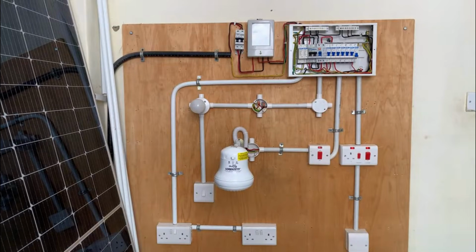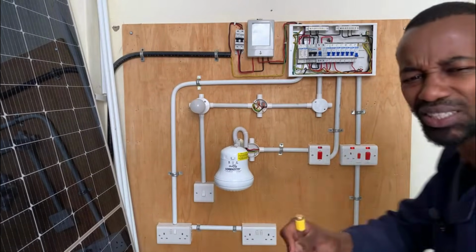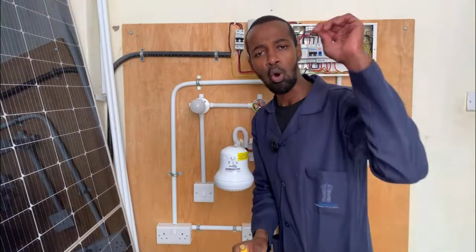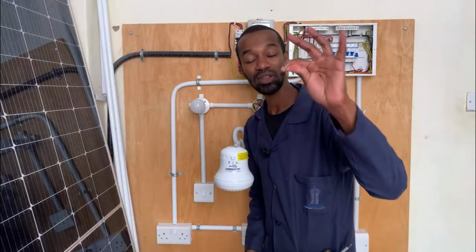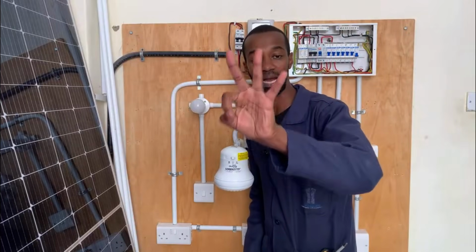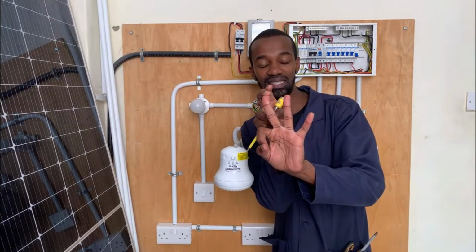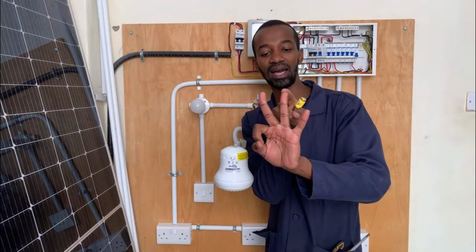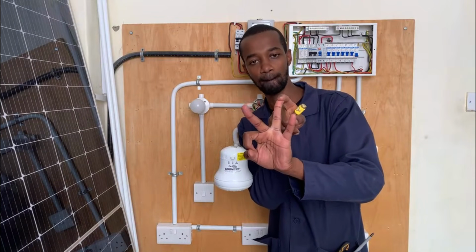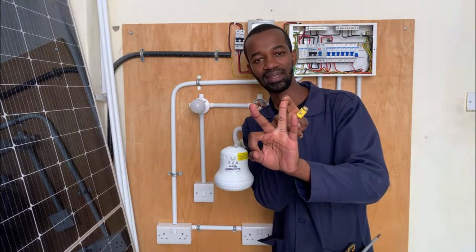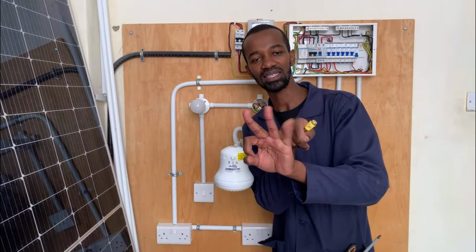So what happens in that scenario? That MCB will trip. But now, my top boss, we don't want to shut down the whole lighting in that home. How do we ensure that? We come up with several circuits. We can even come up with 3 circuits. A circuit that activates the security lights and the lighting in the common areas. Another circuit which activates some parts of the home, let's say the dining room, the kitchen and the corridor. Another one is the bedroom or bedrooms as well as the sitting room.